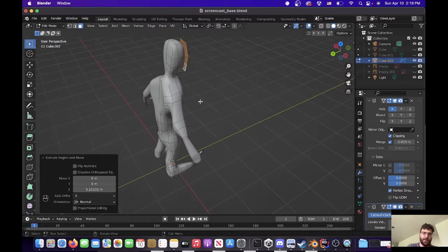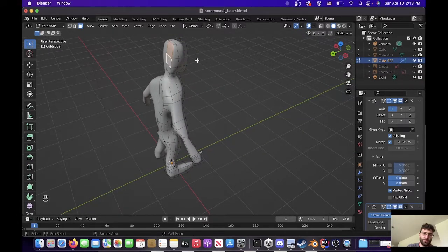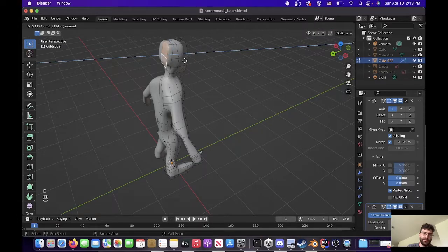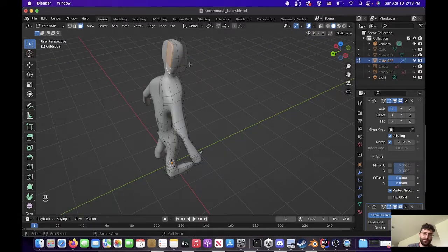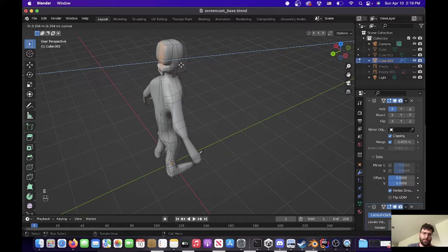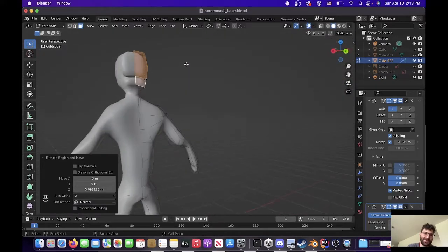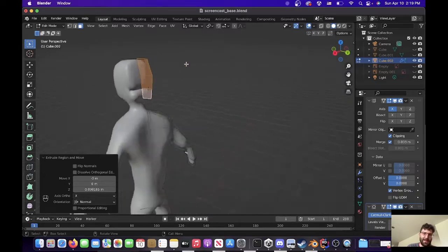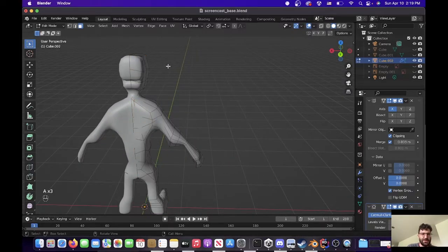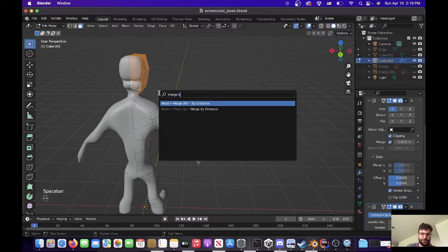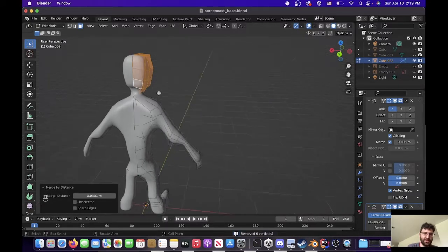And then from here, maybe extrude these out. Nope. Third one. Extrude. Oh boy, that's not good. So something's wrong there with the geometry. Which is a case where if you do the cleanup, merge by distance, that kind of fixes it.